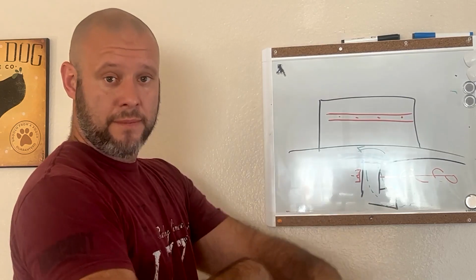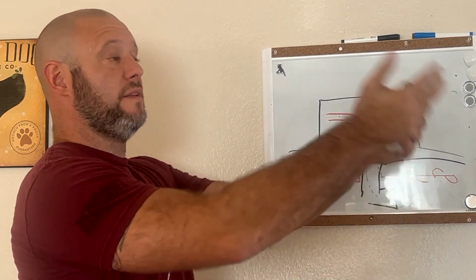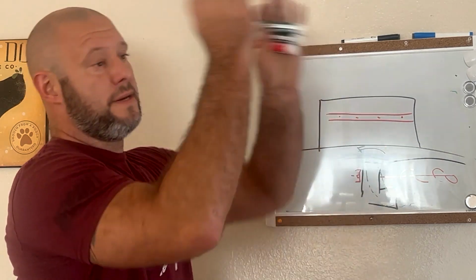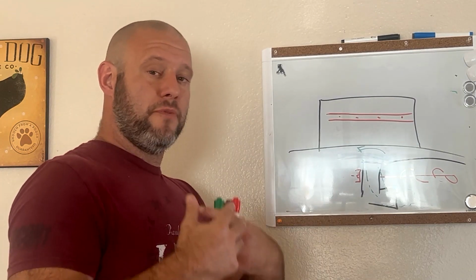That's overturning. That could be too much lateral earth pressure pushing onto the retaining wall. It could be insufficient retaining wall design. It could be the footing was built wrong and it's just not enough, and it's pushing the whole thing over. This is starting to help you generate what type of repairs you can do.